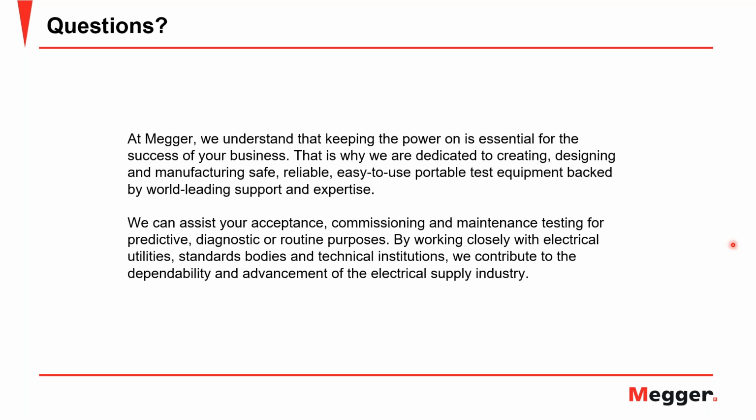Thanks, Abel. Our next question is over to Guillermo. Guillermo, what is the difference of MTA and ECA? Okay, so ECA is the characteristic angle. I mainly know of GE relays that use that terminology, the ECA, and Abel mentioned it at the beginning of his slides. It's a compensation angle that GE uses to calculate the MTA.